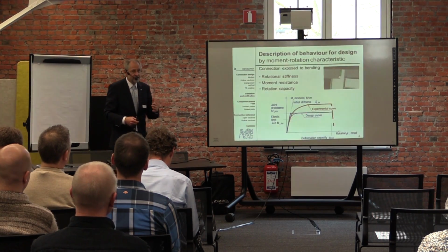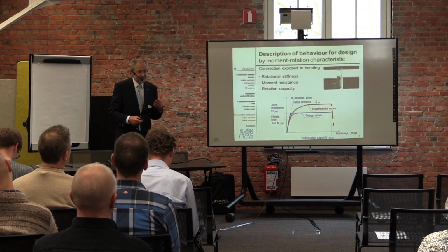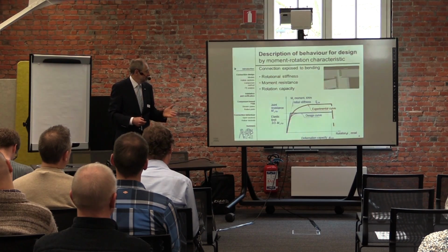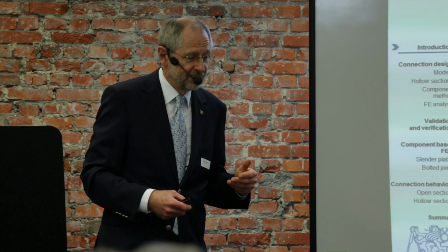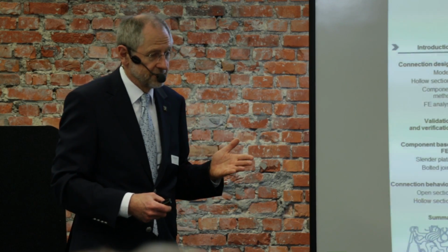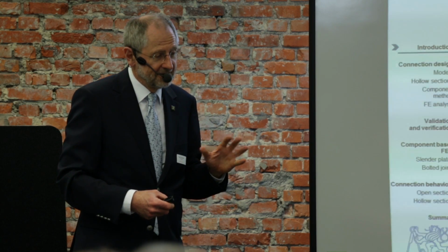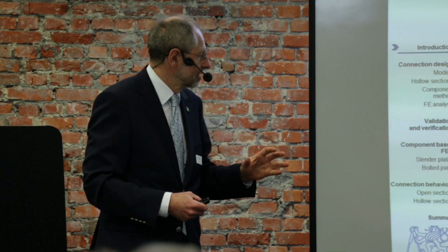We are going for yielding of the material, and of course it's not true, but it's a very good engineering judgment, and our design for steel elements is based on this model, and it was previously used also by our grandfathers for connections. Of course, there are some more complex things: for bolts and for welds, we really take the resistance.